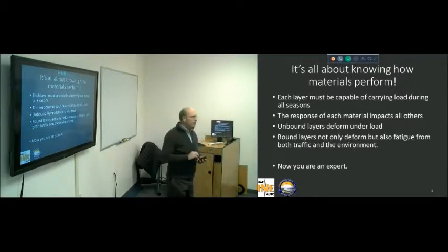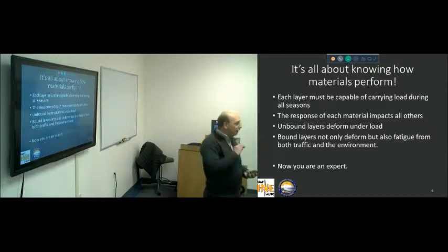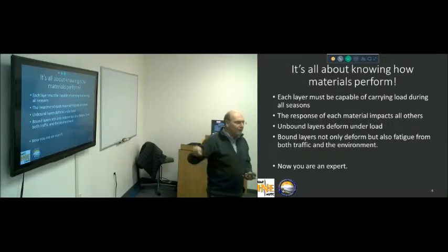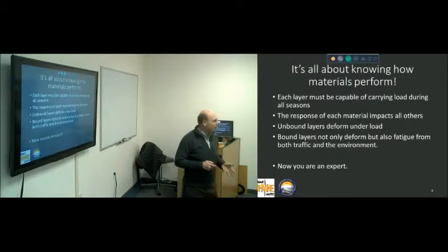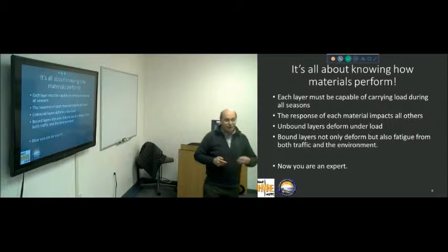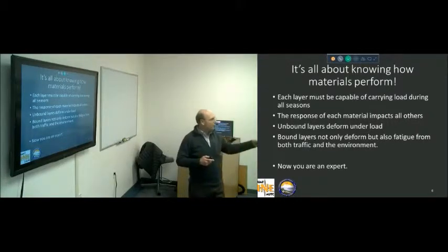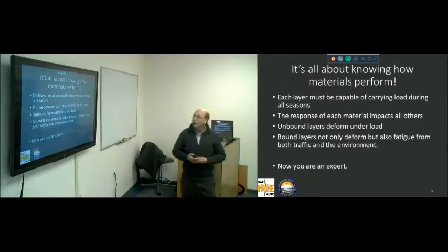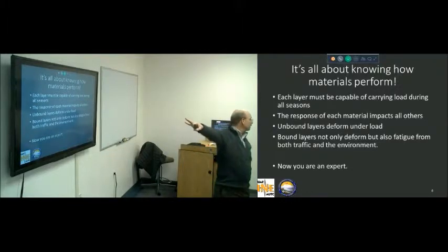And if you don't understand the materials, you can't do a very good job of designing your pavements. I don't care how good you are at running the mechanistic design software that we have. That's really easy to do, but the material properties that you put into that are critical in order to make it work well for you. What I've seen on a number of occasions, people pull values out of the sky, or they pull out values that make the answer that they want come out of it, and it doesn't necessarily represent what's going on in the field. If you truly understand these 4 points, you're an expert in pavement design.